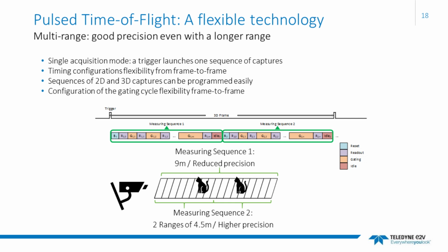First, it allows us to reduce the light pulse width and so to increase the precision of the detection, but it also reduces the required dynamic range because the distance range is smaller. But in the end, an object can be detected over the larger range from 1 to 10 meters. And when the object is moving, it switches to another configuration to track it.